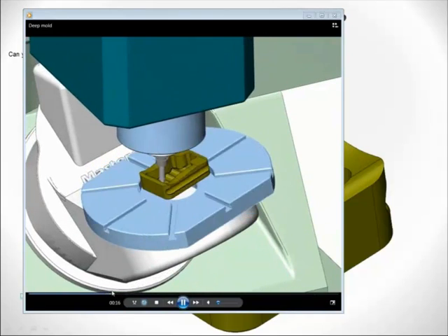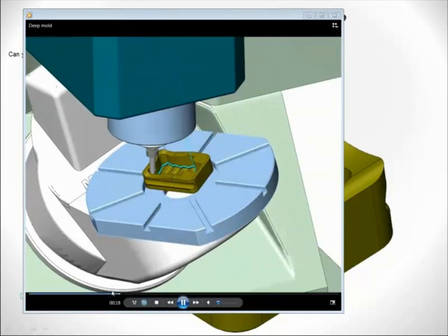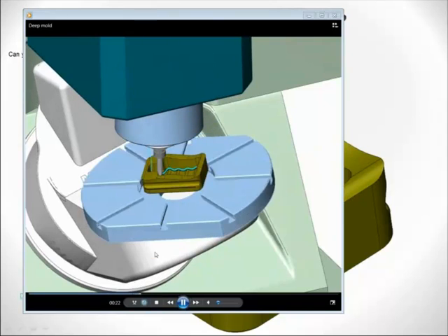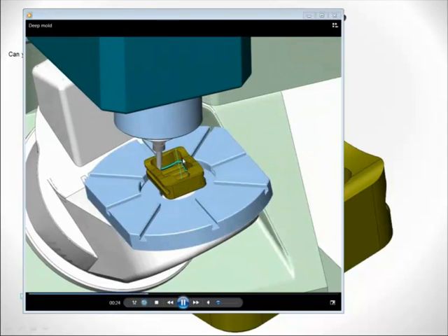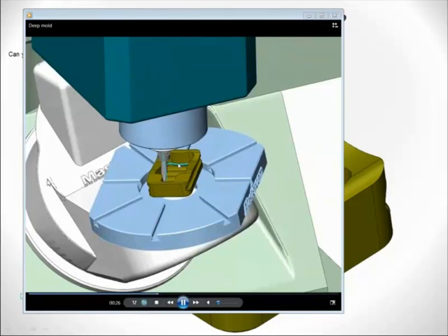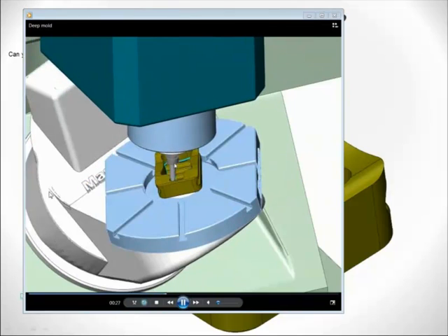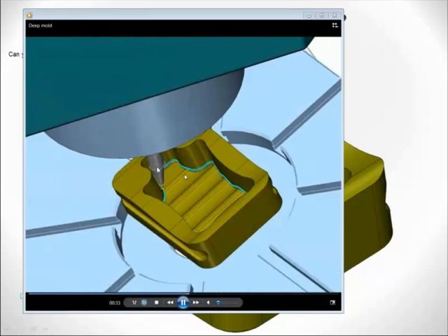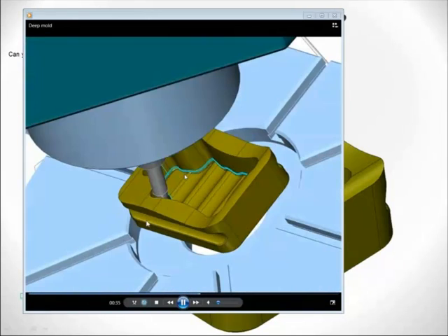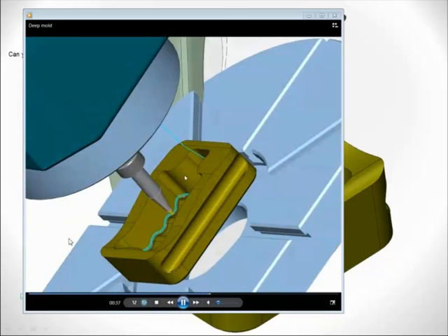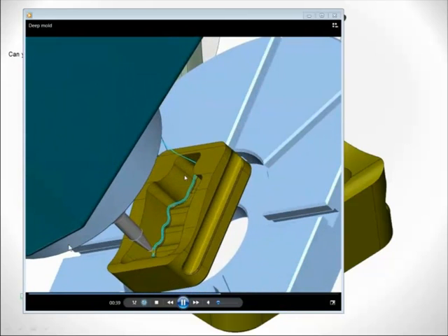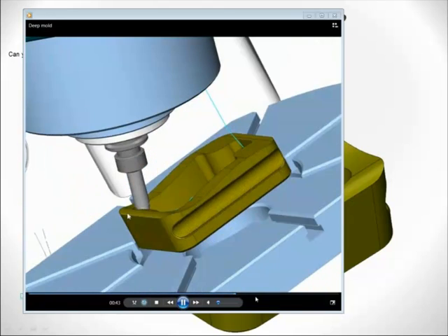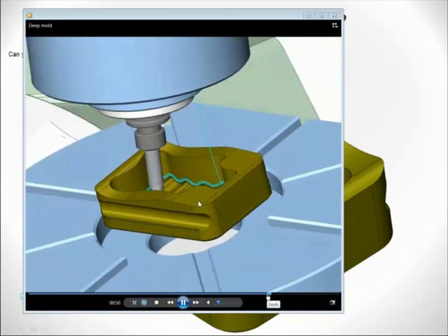So as you can see, we are tilting away. We cut everything 3-axis, cut the walls, cut the floor, but there is material remaining at the bottom of that fillet. So we will do some multiple passes that are all parallel to the floor, and they will go down on the wall to blend into that fillet. I realize there may be some delay in this as you're looking at the display.